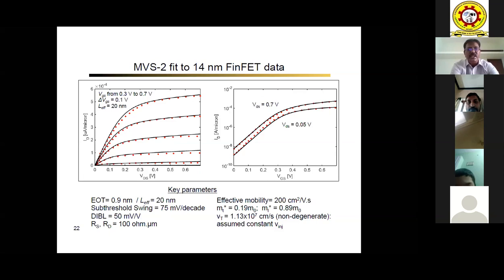So these are the parameter values input before the simulation gives you the output waveforms like this. So thereby these parameters are already listed out. If you say EOT is 0.8 nanometer, I had a better result, then your benchmarking is not right. So you need to go with the same kind of key parameters before you use a benchmark results.